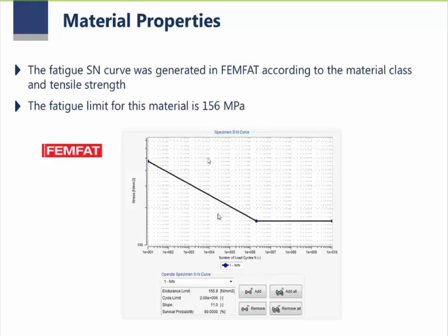Of course, if you don't want to give the software the opportunity to generate the curve, you can import it from some tests, for example. And here is the endurance limit of the material, or the fatigue limit of the material, which is around 160 megapascal, which is high for this material.